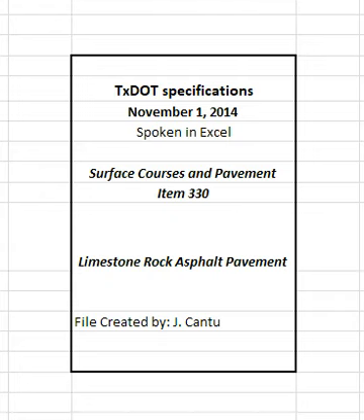Operate vibratory rollers in static mode when not compacting or changing directions, or when the plan depth of the pavement mat is less than 1.5 inches. Unless otherwise directed, start by first rolling the joint with the adjacent pavement and then continue by rolling longitudinally at the sides when rolling with the three-wheel, tandem, or vibratory rollers.